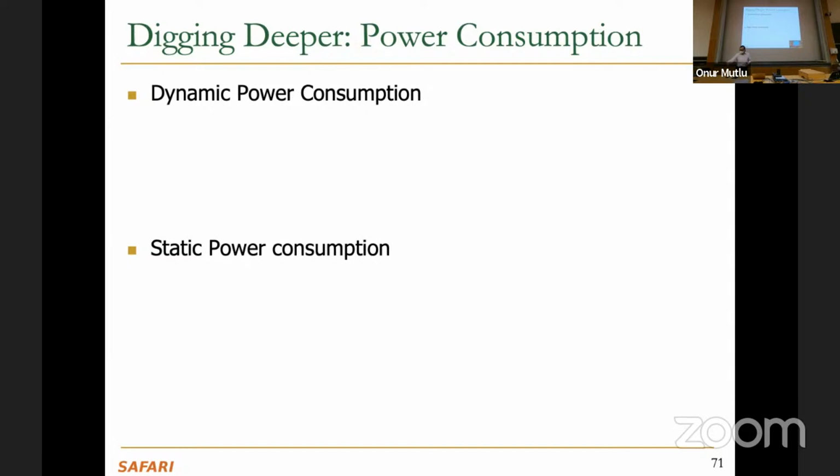So for example, this cell phone over here is not doing anything. Well, I hope it's not doing anything, but assume it's not doing anything. It's still consuming power, it's leaking. As we discussed, the DRAM is leaking, for example, but other circuits are also leaking. So basically, you're losing some values, and then you need to refresh them. But sometimes you're not even losing the values because you don't need to switch the circuits. But even then, there's leakage from the high voltage path to the low voltage path that's consuming power. That's static power. Let's talk about dynamic power.